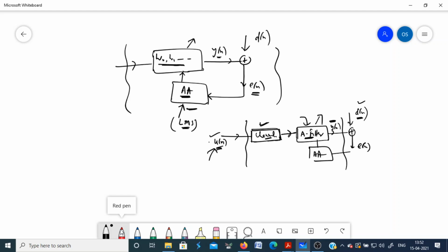And then this training sequence may be given from time to time, because this channel is random, so its response may change after some time. So after every half an hour or maybe 1 hour, you again give a training. So in the training, you again give a pulse or a PN sequence here, that is again given to this receiver. It will again adjust its filter weights. It will change its response in order to again satisfy this condition, in match with the impulse response of the channel.